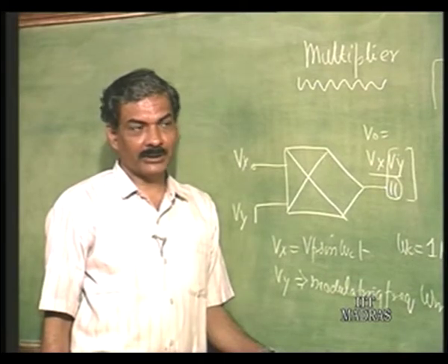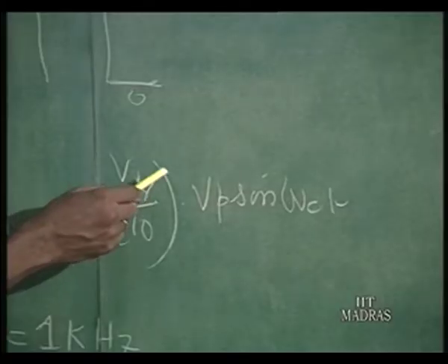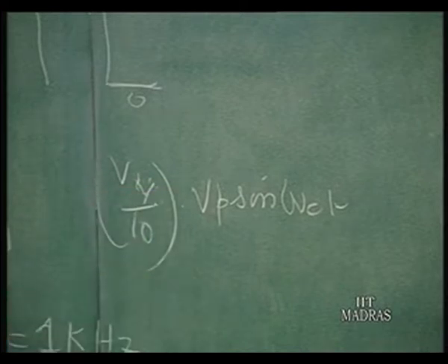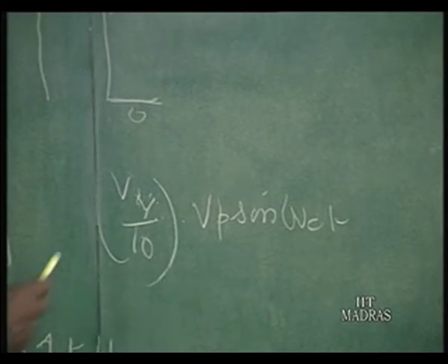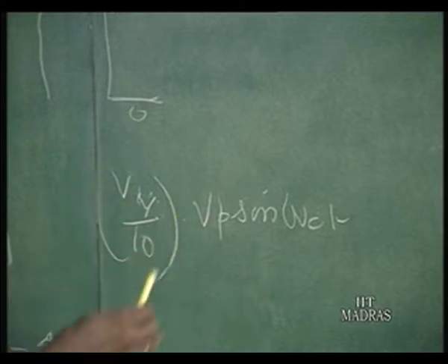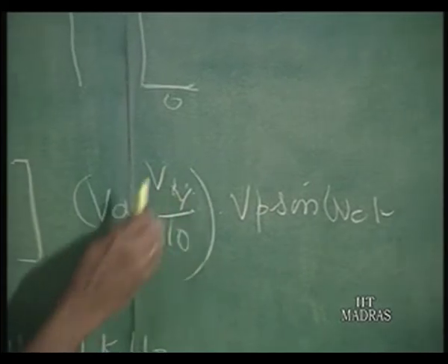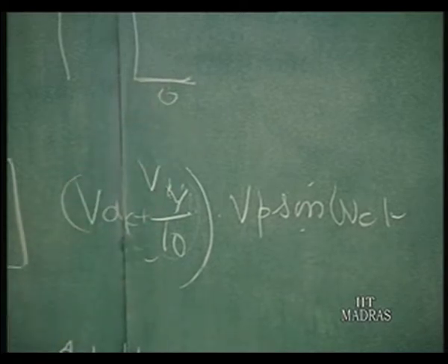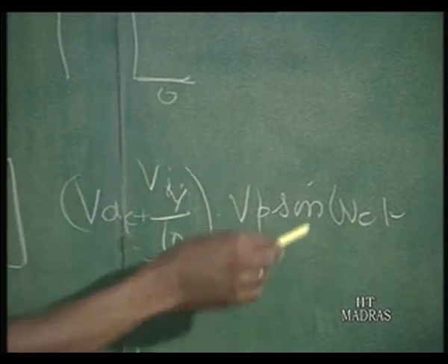In the last demonstration you saw the gain was varying from 0 to 1, 0 at some interval and 1 at another, it is called keying. Now, if you want to convert this into AM, amplitude modulation, you have to make it non-ideal. We want the gain to vary from some value to some other value. That means we have to apply a DC plus the modulating frequency. The DC will bring the carrier and the modulating frequency will change the amplitude from some value to some other value. So, we have now had an arrangement where we have added the DC and the square wave at 100 hertz. So, that output is an AM.